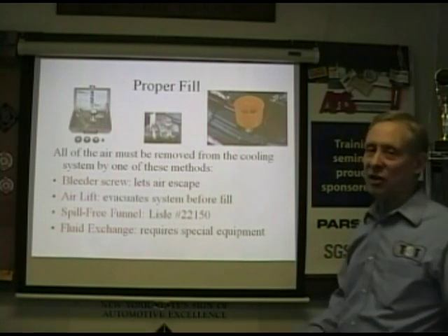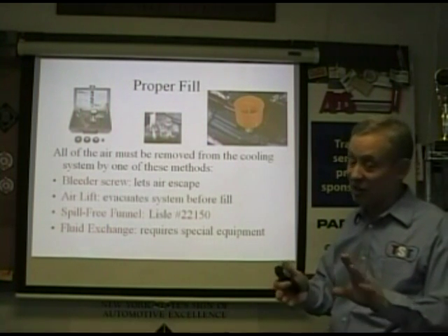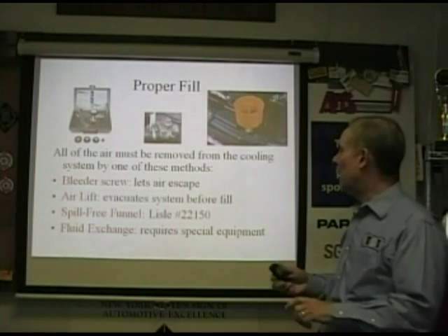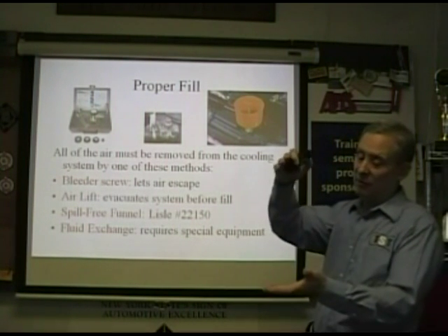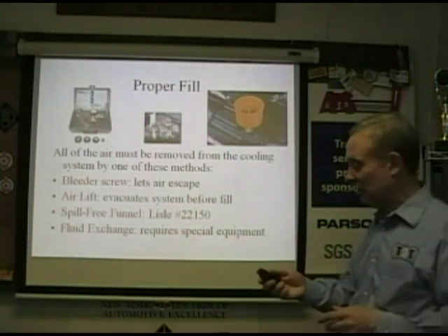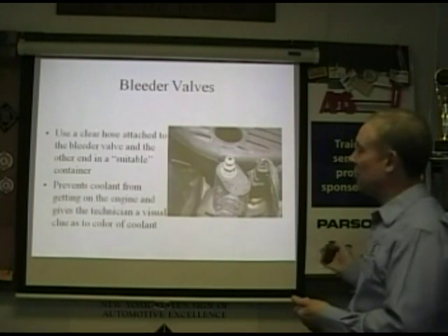Proper fill. You got to make sure that you bleed it out the bleeder screw. Air lifts are good, or any other technology like that that takes out all the air. Use a spill-free funnel that makes it so that you have this fluid cap over your system, so it pushes all the air bubbles out. The idea is fill it completely, get all the air out, and make sure it's clean.